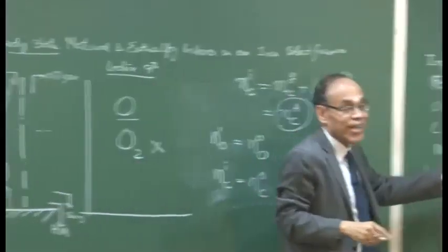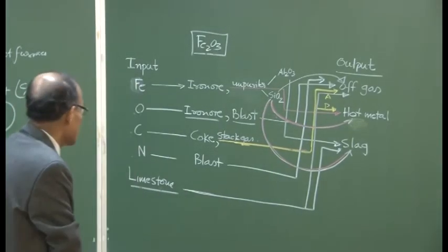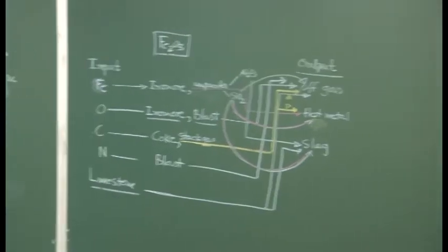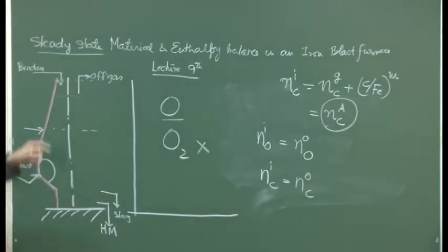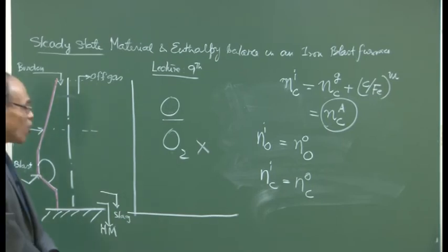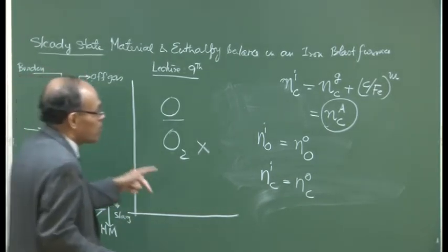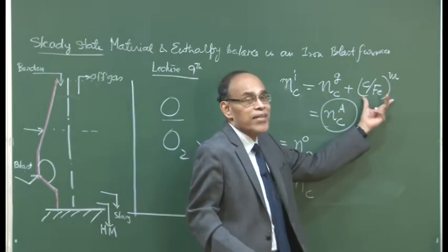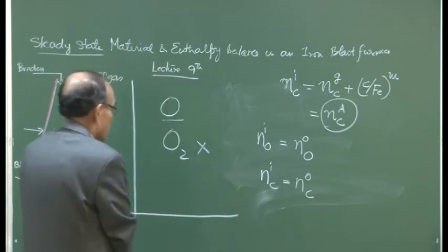Also we know that the slag has no capacity for carbon; slag does not dissolve carbon, and because we have oxygen here, whatever carbon is there will tend to get oxidized. So the slag cannot contain any carbon, and barring the passive carbon, the entire amount of active carbon is sitting in the gas phase itself.